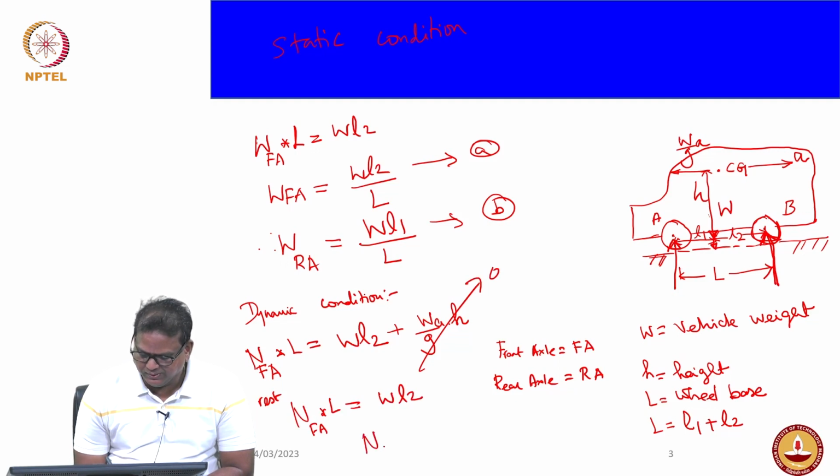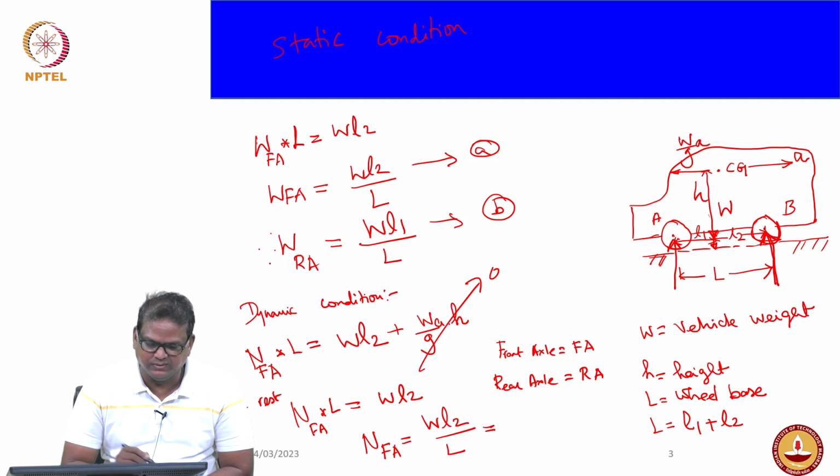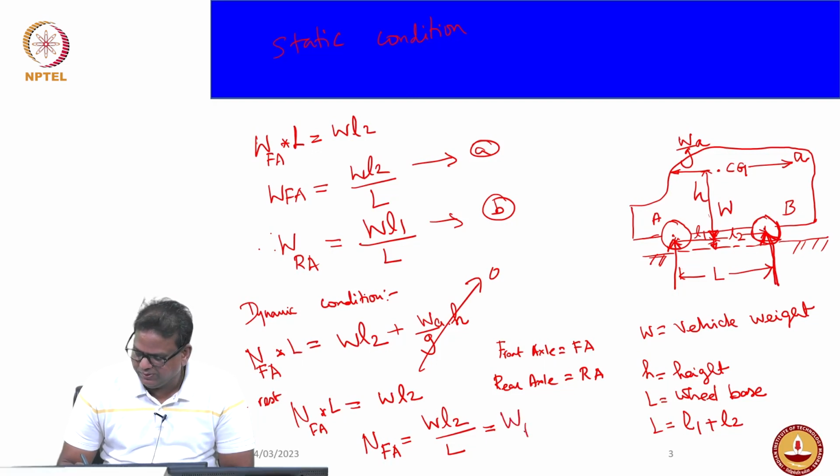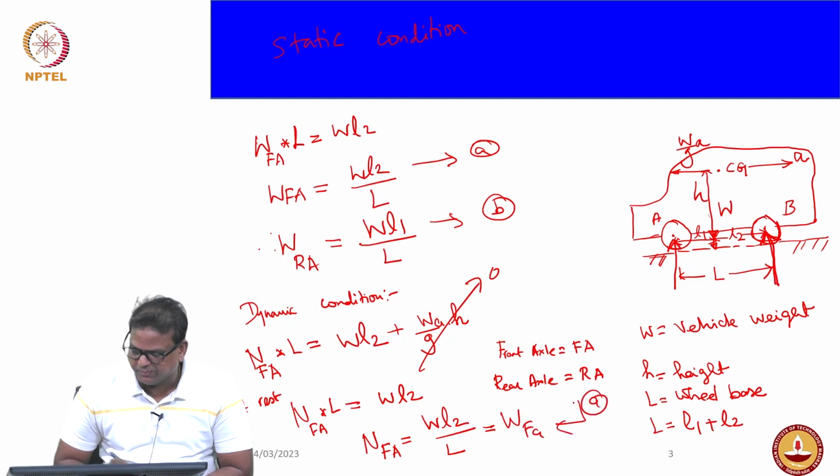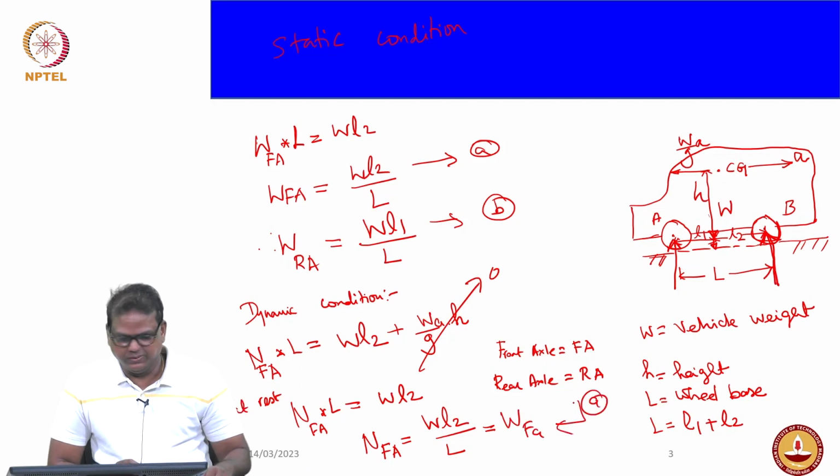Otherwise, the reaction force at the front axle equals WL2 by L, which is the same as WFA from equation A. This is your observation.